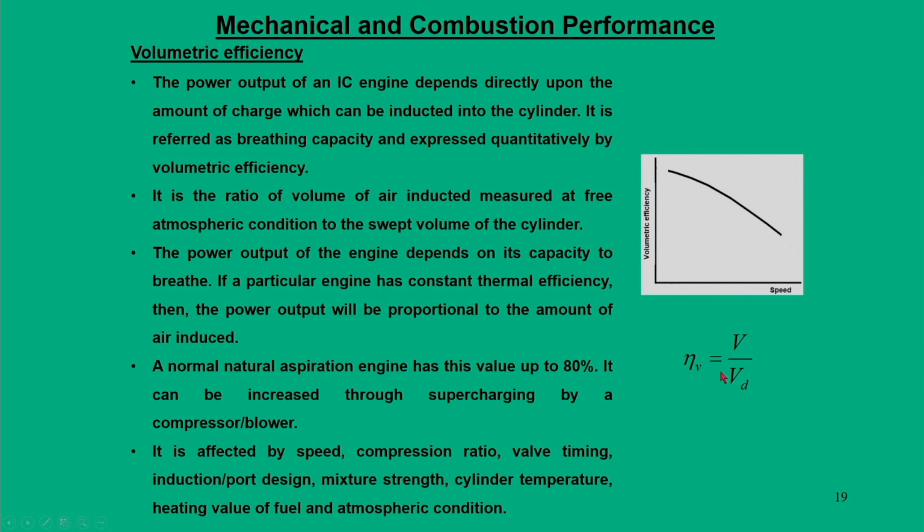So, normally this volumetric efficiency term comes up for gaseous fuel, and it is not so significant for liquid fuels. It is a very significant term for gaseous fuel. Most of the engines that use biogas or LPG or natural gas, the volumetric efficiency plays a role, because the fuel has to be linked with air, it has to be mixed with air.